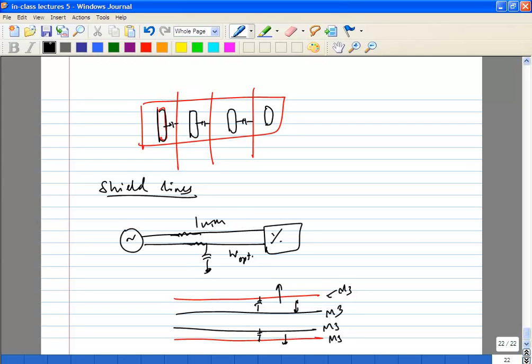Which is why you're not going to add on top of it, you're going to add to the side. On M4 or M5 on top of this, you typically don't want to cross. You don't want to cross these two sensitive lines at all. Now there may be cases where you are forced to cross, in which case you make those crossing lines extremely thin and short. Obviously you don't run lengthwise, you run perpendicular. That is one thing you can do.